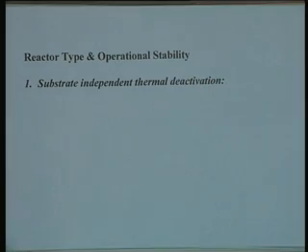The third item we have seen is the inhibition pattern which the kinetic reaction follows, and probably another pattern which is very important in analyzing immobilized enzyme reactors is the reactor type and operational stability. As I mentioned, I think one of the most important motivating factors for looking at immobilized enzymes was the operational stability. That means we can use them continuously over a very long period of time, and we must also look at how the reactor type influences the operational stability.